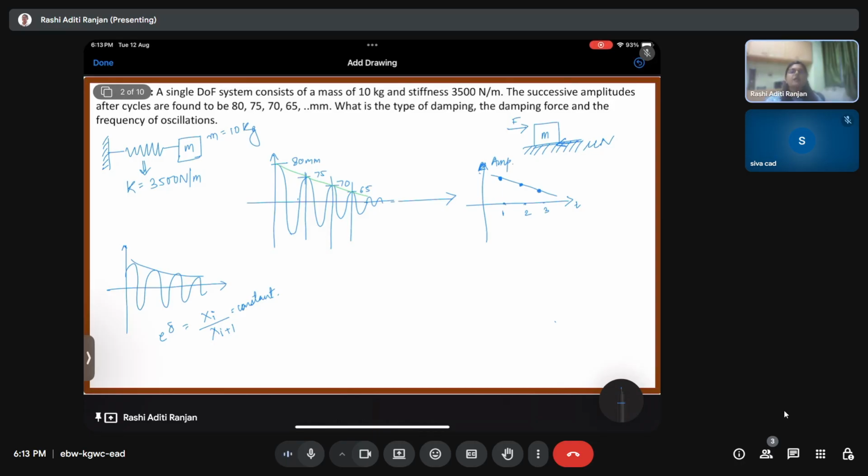Coulomb damping, where we actually use the effect of friction because of which the system gets damped, right? Now, or it is losing energy. Saying damped is not the correct word. This is essentially losing energy because of that friction, right? Because the system is trying to overcome the friction, because of which it is losing energy. Okay. Now we know that this is a case of friction damping.